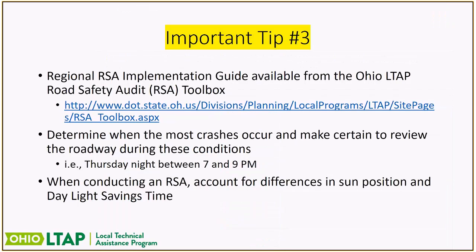So important tip number 3, the Regional RSA Implementation Guide is out there on the Road Safety Audit Tech Transfer Toolbox. So use that as a tool when you're putting things together. You can get prompt lists from there and other information. Also make sure that you determine when are the most crashes actually occurring and try to schedule your RSA to happen during that time.